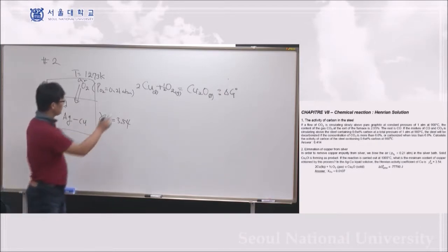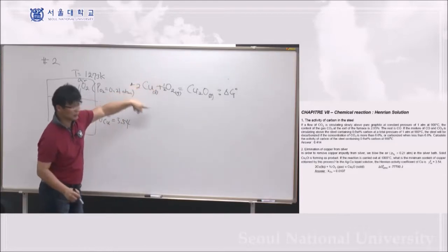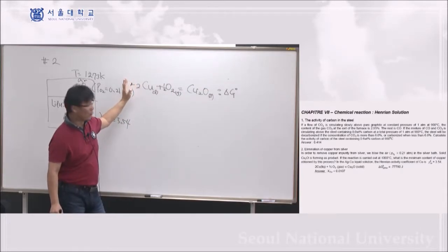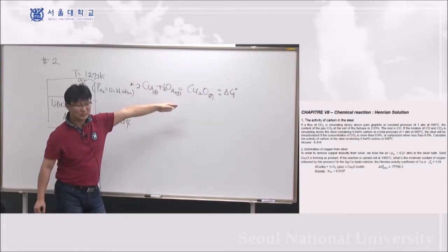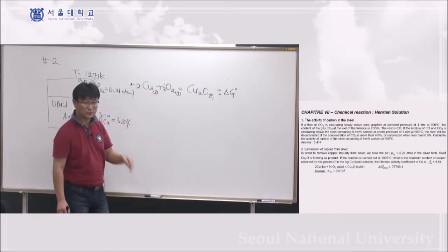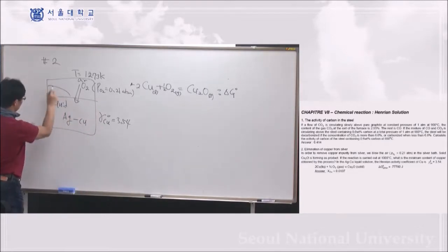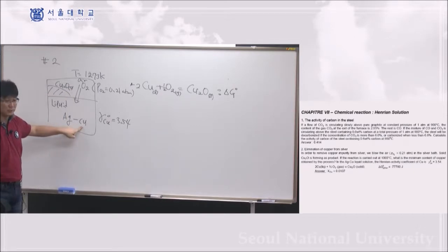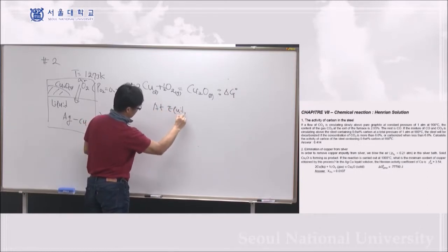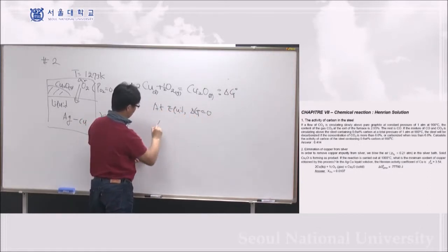Okay, however, this chemical reaction Gibbs energy is independent. As I mentioned, when you write this down, you don't know where you want to apply it yet. This is just pure copper and oxygen reacting to form pure copper oxide. So when you do the reaction, you will form Cu2O solid phase. This is the question: what will be the minimum copper content? This means, what's the equilibrium copper content here? So, at equilibrium, delta G should be 0, so it means delta G naught.